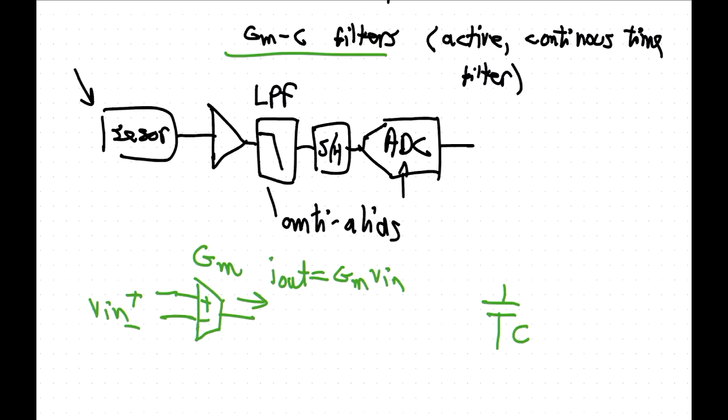The other thing I should say is that it is convention when you look at transconductors like that to define the current being positive when it flows out. That is actually also the case when we look at operational transconductors, because if you don't do it like that, when you start to make negative feedback and so on, it goes the wrong way around. So this is just something to keep an eye out for. Always make sure you know which way the... Isn't that how we usually do it?